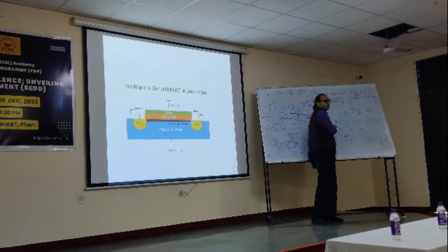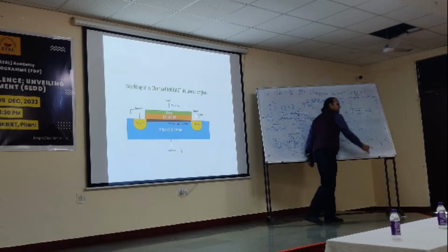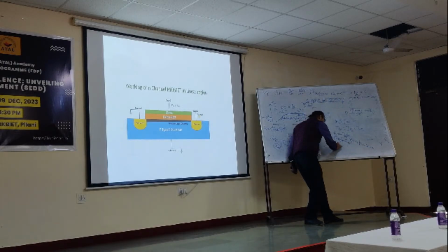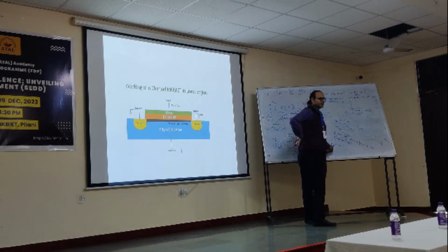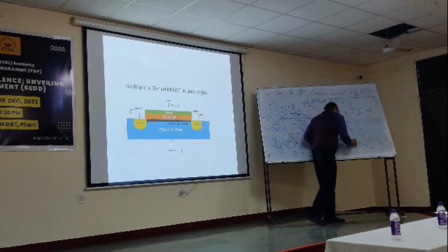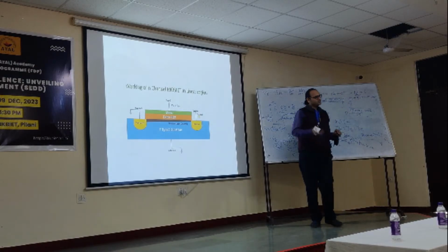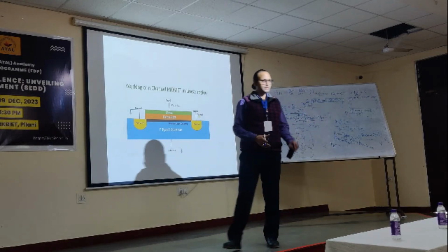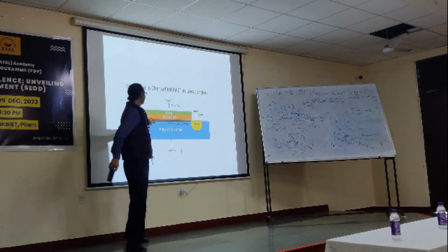The most favorite current gain for the amplifier design engineers, IC by IB. And we want this to be maximum. So how is that possible? We want this to be minimum. Sometimes in solving numerical problems, we directly write IB is equal to 0. It is totally unethical, right? So we want this current to be 0. So in MOSFET, this base is analogous to what? Gate. So we totally isolate it. Rather than creating disturbance, we isolate it just like this. It becomes simpler.